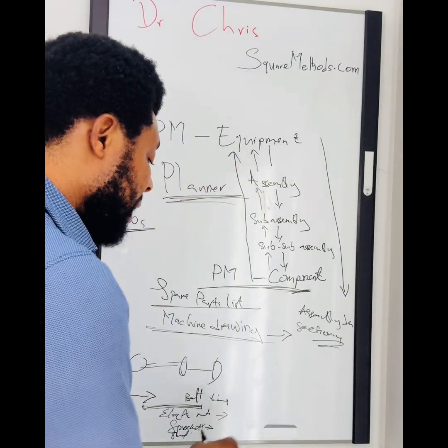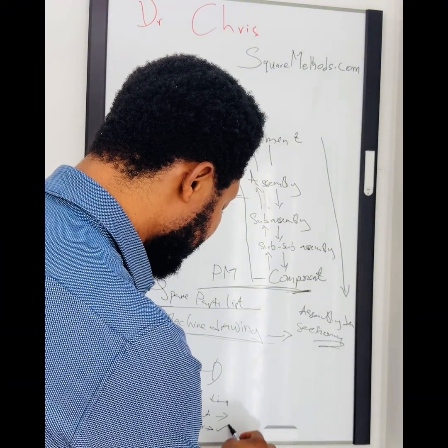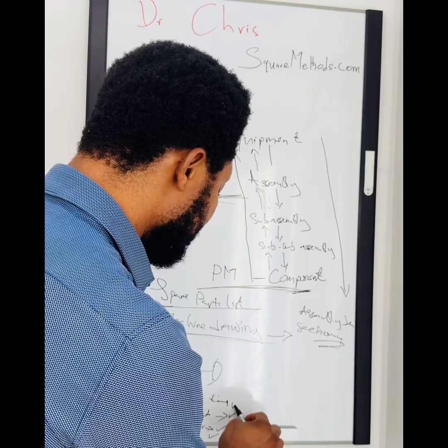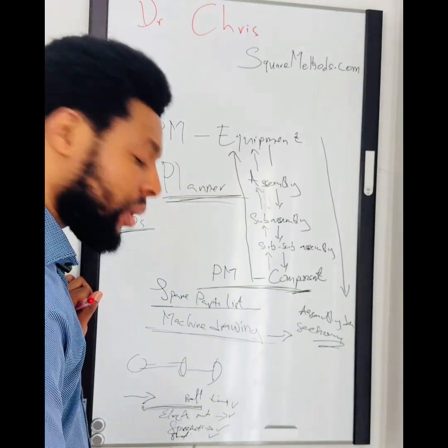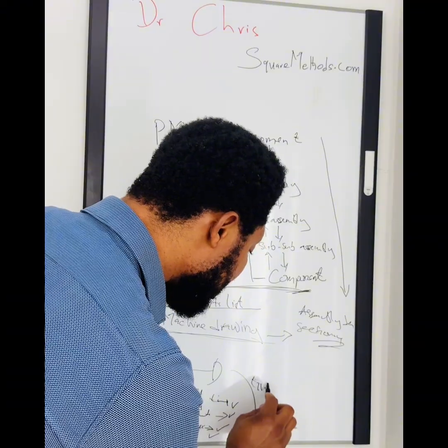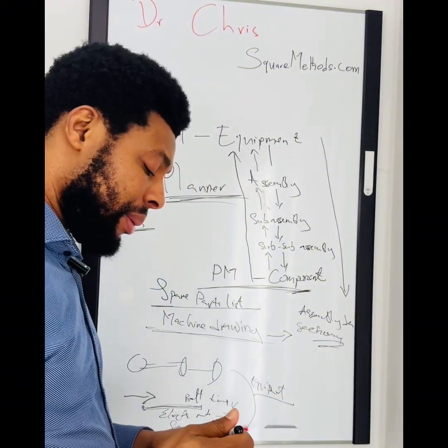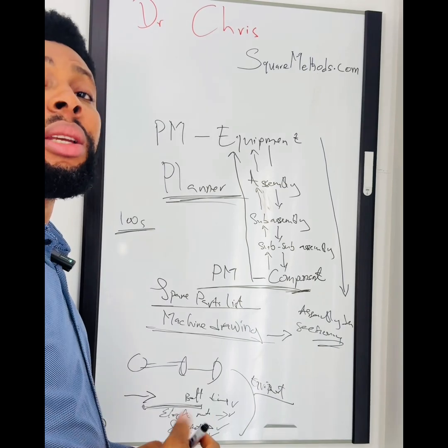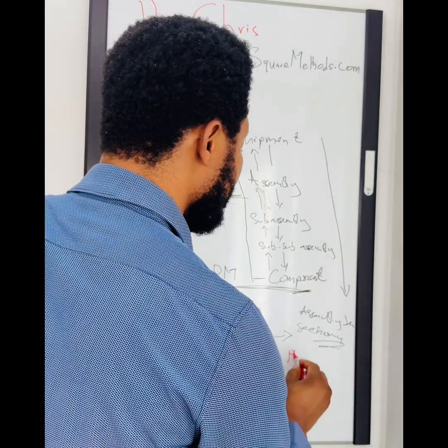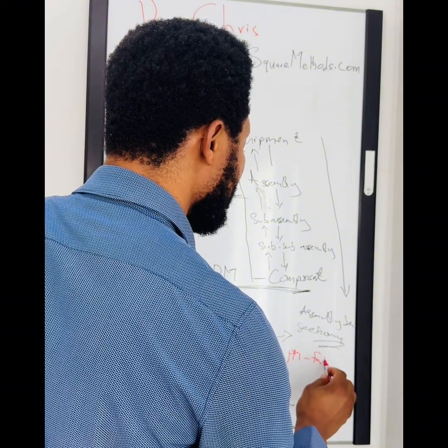So when you are defining your PM, you have to define PM for the sprocket, for the shaft, for the electric motor, for the belt, not for the equipment as a whole. If you do it for the equipment as a whole, then you are breaking the rule that I mentioned earlier. Your PM is supposed to target failure modes.